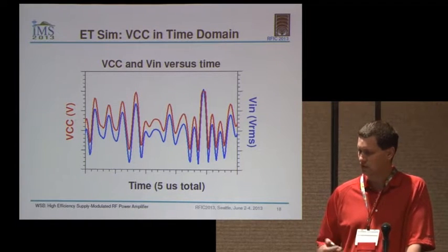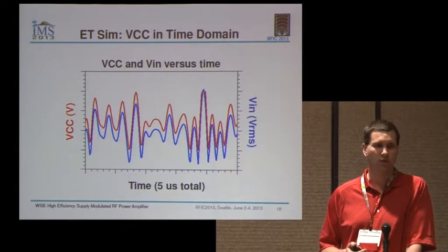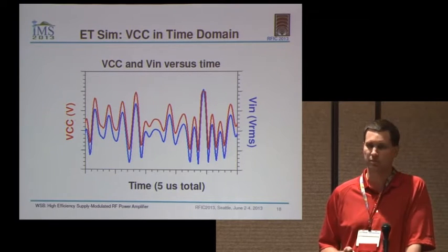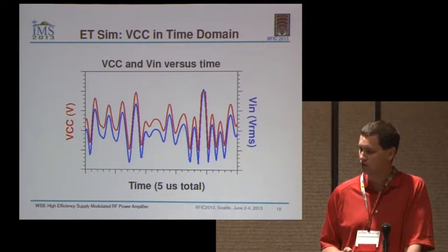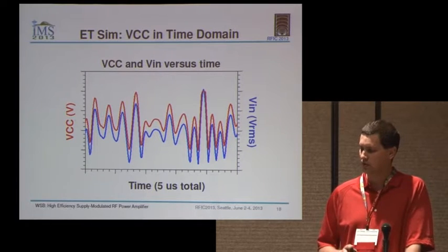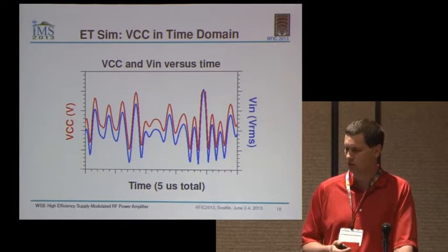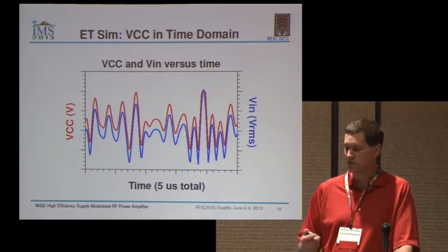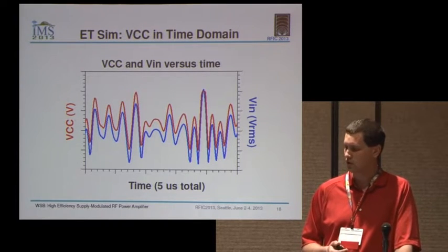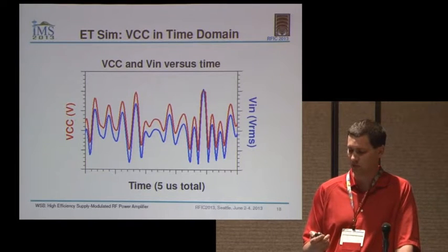This is just 5 microseconds of the waveform, meant to show a demonstration of the characteristic. And if you look, there's a peak on the right side, like 3 or 4 peaks from the right, a large one where you can see the VCC max clipping is occurring. You can see where the blue actually exceeds the VCC voltage a little bit there.